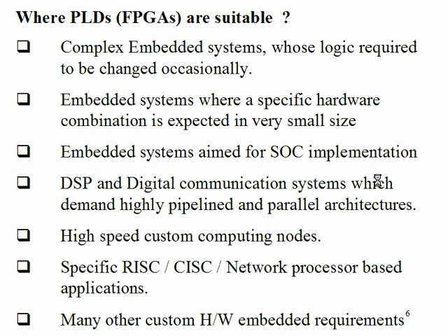But when I come to a motherboard, my speed is getting limited, isn't it? Can anybody talk about the specification of your computer? FSB, front side bus. Any computer, when you are trying to purchase, a very important feature is the front side bus speed. That is basically the clock of the data buses which are running on the motherboard. Today front side buses are coming up to around 800 megahertz. Of course there are some techniques by which you can go up to gigahertz also, but in commercial products, the clock with which the data is moving on the motherboard is 800 megahertz only.